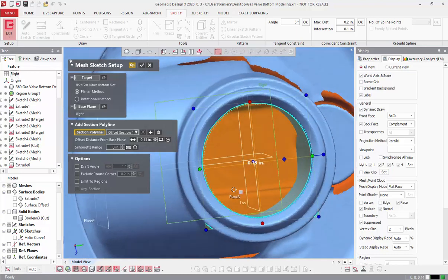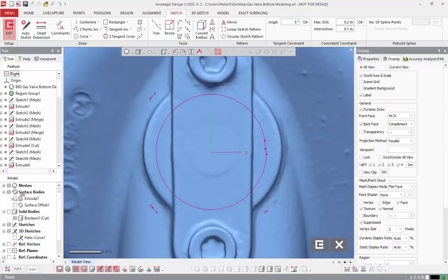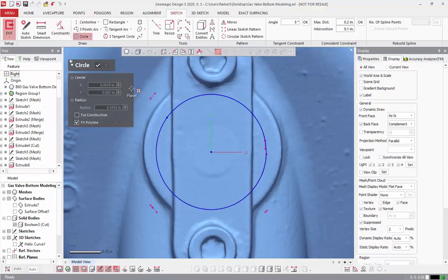That's going to make sure that the estimate draft angle tool works properly. There's no other stuff in there. And it's saying I got about a degree of draft. So I'm going to say that there's about a degree of draft here. 0.8954 is as close to 1 as I need it to be for the draft angle estimator.